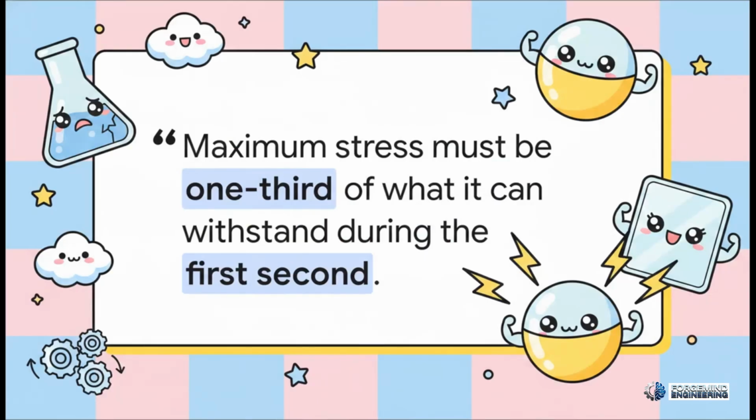This brings us to a completely non-negotiable rule of thumb. To withstand a certain load for 1,000 hours, the maximum stress applied is about 1/3 of the maximum stress it can withstand during the first second. To prevent sudden, catastrophic failure from what we call static fatigue, we strictly enforce this baseline. The long-term load limit on any glass component simply cannot exceed 1/3 of what it handles in second one. It's our ultimate safeguard for long-term reliability.